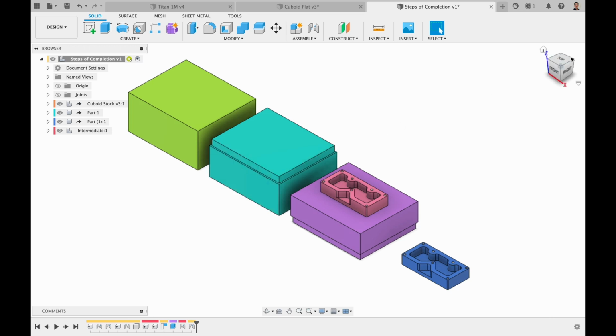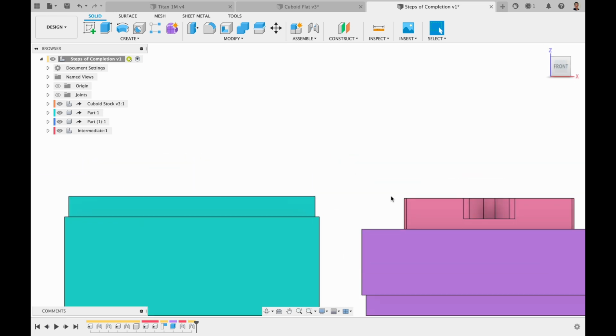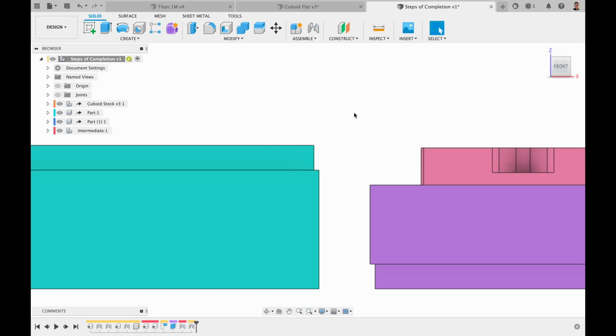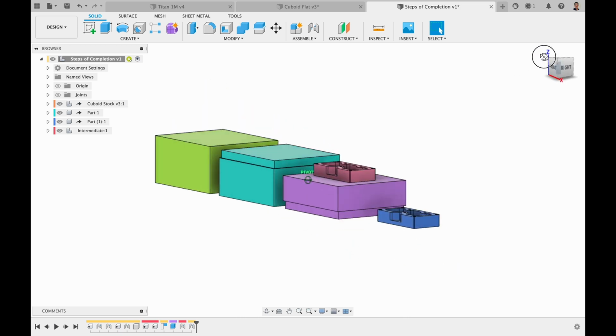Now we use those precision faces to hold on to it on the bottom, and we machine out our part. Now the part is also slightly lower than the surface of the top because we assume that that side is still rough. After we do that, we can't really machine all the way through because we have no ability to access what's behind the part.